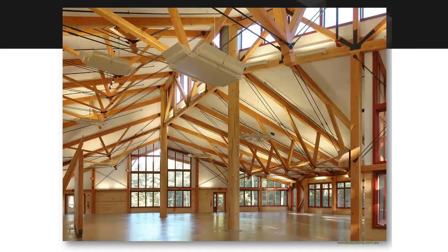In this photograph, you can see a large number of compression elements. You can see vertical columns, so that those vertical columns would all have their capacities evaluated that way. You can see some major trusses that are running from the back of the photo to the front of the photo. Those trusses incorporate both tension and compression timber elements, and the compression elements would be evaluated exactly the same way as we have just been outlining.